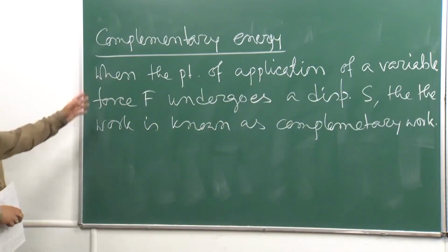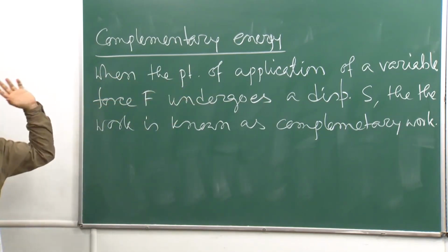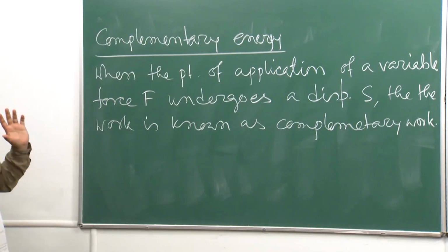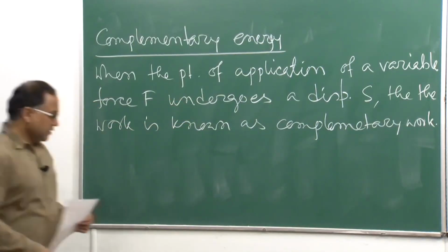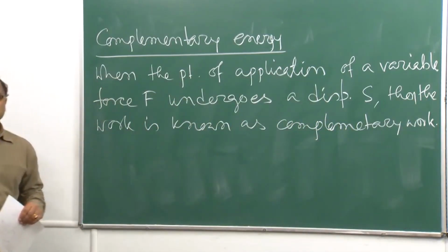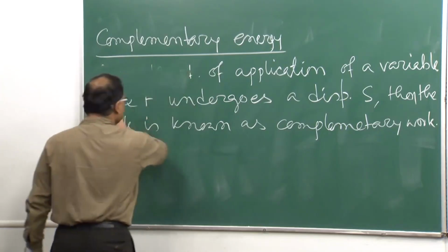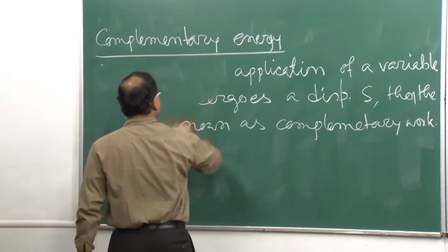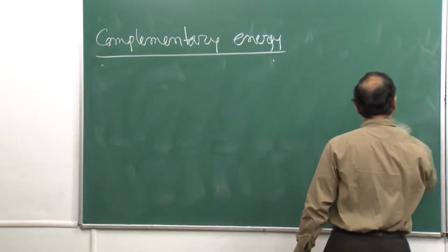So, what does it say? When the point of application of a variable force F. So, in the earlier case when we were talking about the potential energy, your displacement was variable, now your force is variable. Variable force undergoes a displacement S, then the work is known as the complementary work. Now we are going to define the complementary energy. Once this is the complementary work definition, then in this process whatever energy will be stored will be called complementary energy.